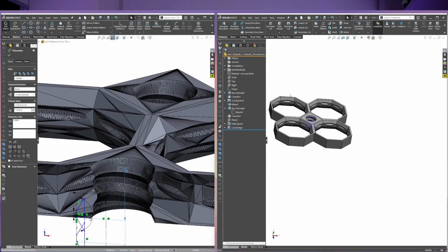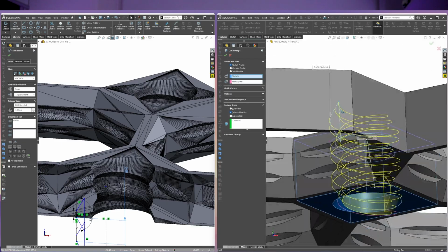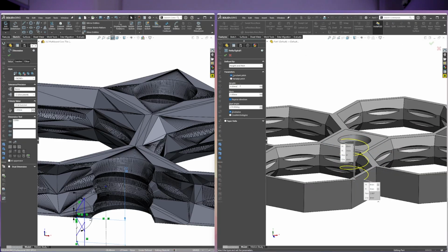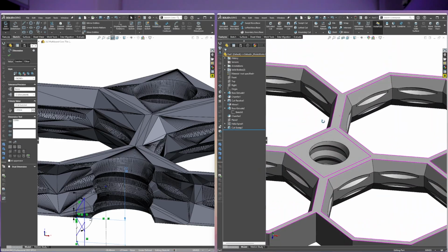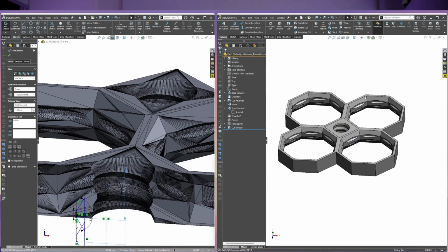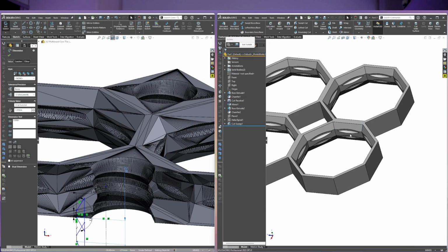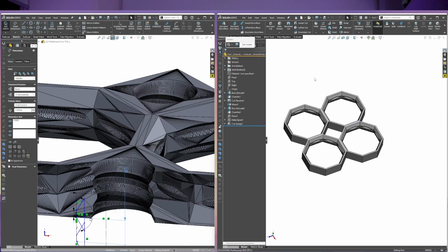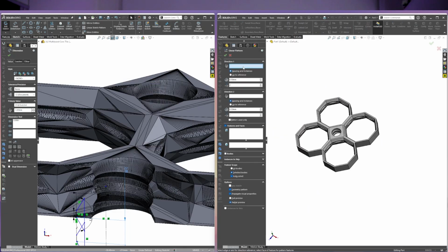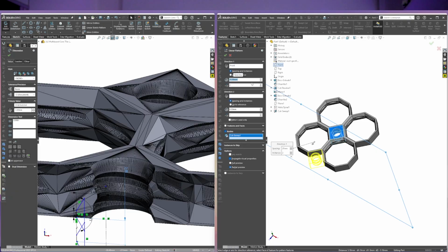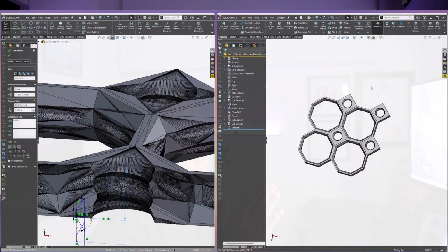Okay, so you can see there with the helix and the cut revolve, that's now created that thread detail. And I'm just doing some checks to make sure that the dimensions I've got for those sections are correct. But once I'm comfortable with that little section, that diamond section with a threaded cut, I'm now patterning that as a body pattern, a linear feature pattern, 2 directions.